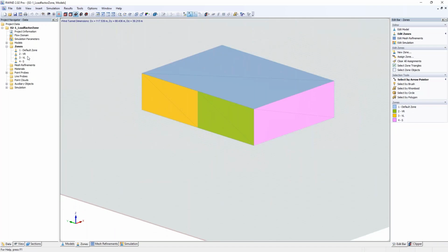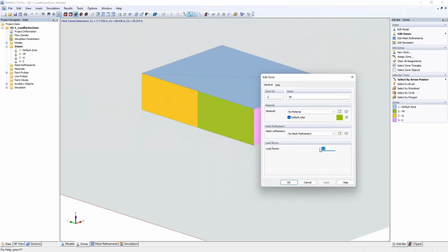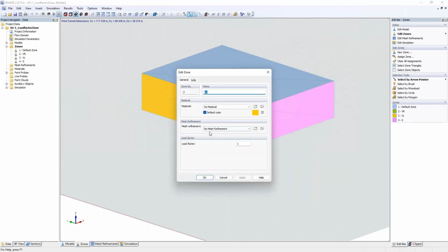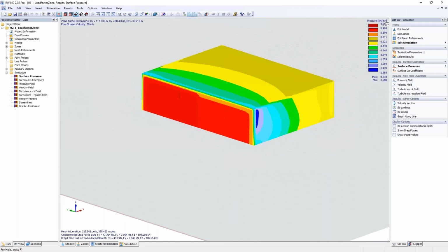And once you have defined these zones, like having your permeable surfaces, you can just double click into the edit zone bar, and maybe you have already seen the factor in here. For my right green side, so half of the front, I've chosen that the factor should be 0.5. Compared to this, the factor on the left should be 1, so that you, of course, quickly see that it's adjusting the results. And just by chance, I have raised the sides to 2. If you then check the simulation results, you might already see a color change in those zones.